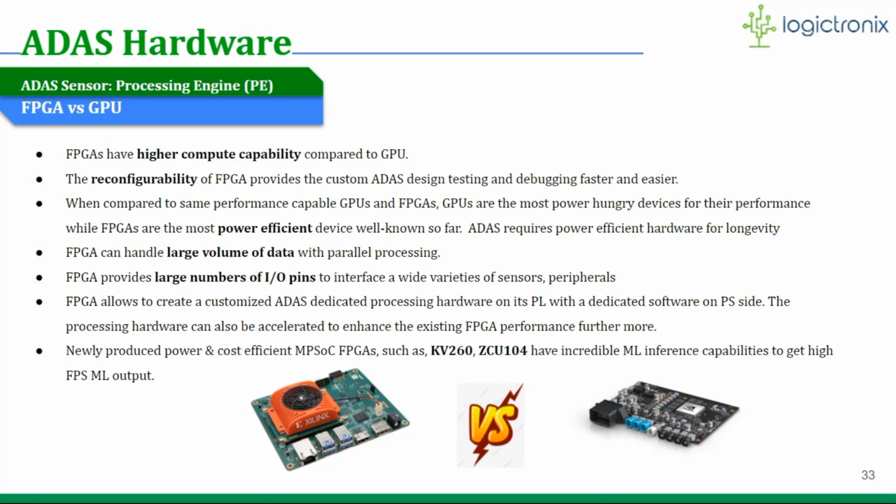FPGAs can handle large volumes of data with parallel processing. FPGA provides a large number of I/O pins to interface a wide variety of sensors and peripherals. FPGA also allows creating a customized ADAS dedicated processing hardware on its programmable logic with dedicated software on the PS side.